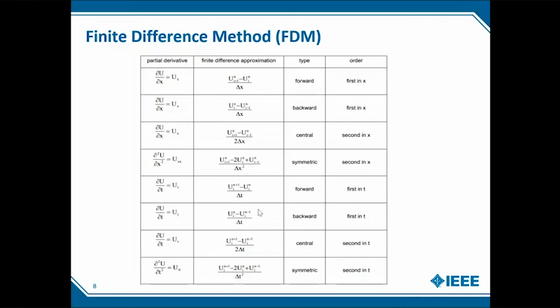So before even going to finite difference method, I want to tell you, why do we need discretization? All the governing equations that we have are basically partial differential equations, and a PDE does not have an analytical solution. So the next step is basically to get an answer to these equations. The next best approximation that we have is we basically convert them into algebraic equations, because we can easily solve algebraic equations. There are multiple numerical methods available out there which can solve algebraic equations. Some are really fast, some are really slow, but it's possible to solve the algebraic equations. And that is why we discretize.